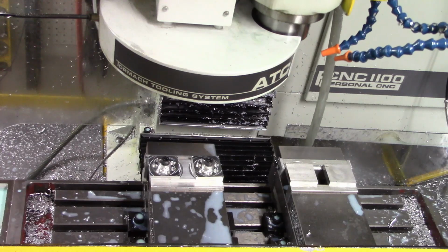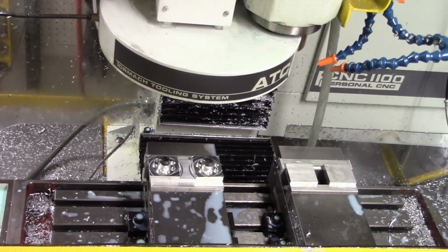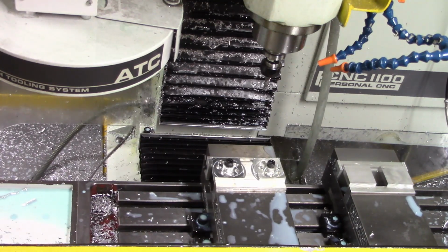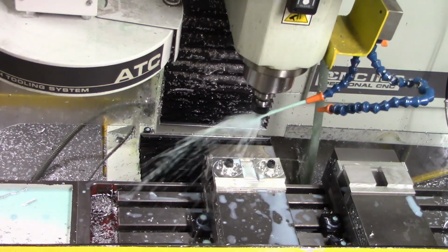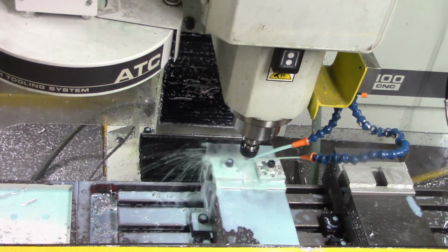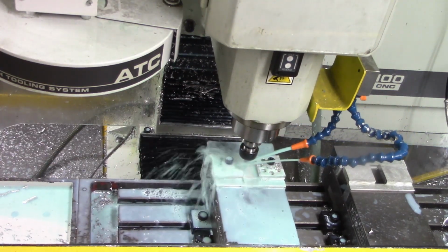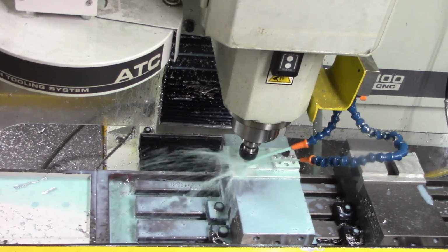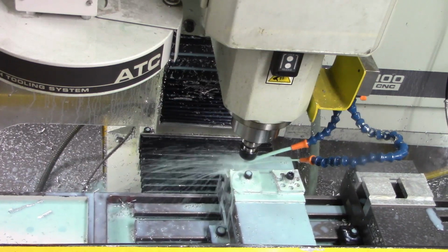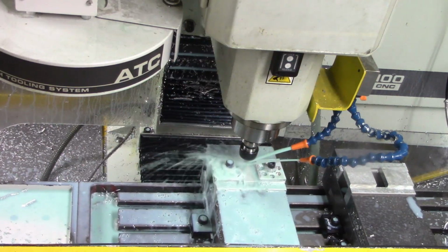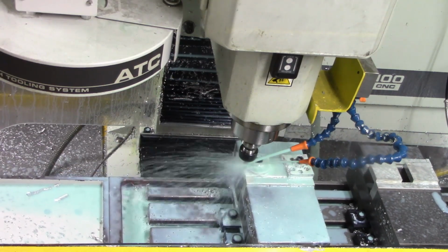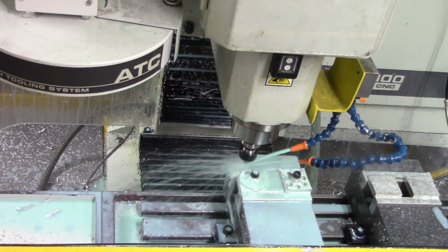Starting with the Lakeshore carbide roughing cutter, starting on work offset 3, which is the left vise. This is the aluminum shredder roughing cutter, and this one is running at 50 inches per minute, doing 2 passes to cut through a little bit over a 1/4 inch, 0.26 of material.